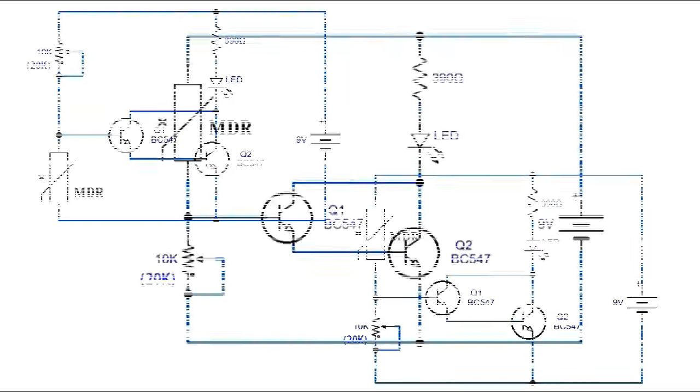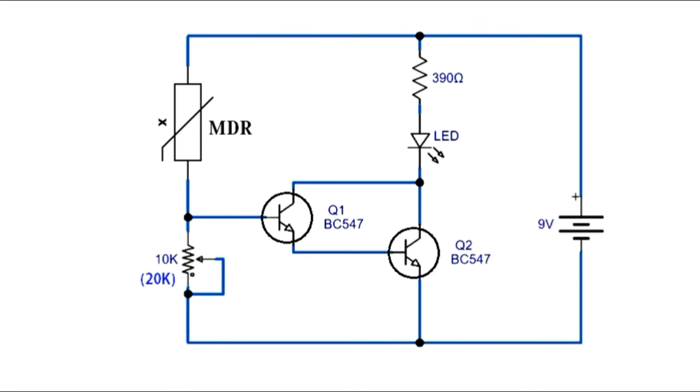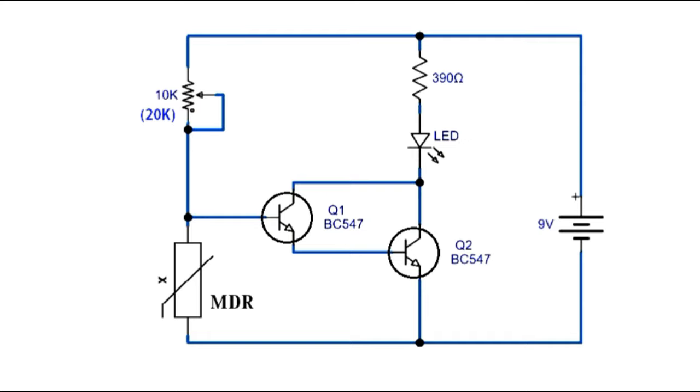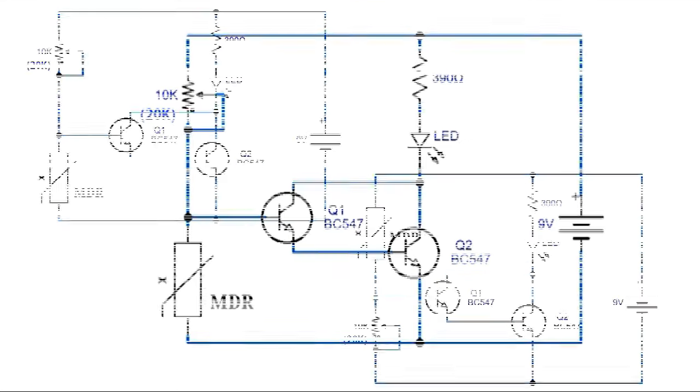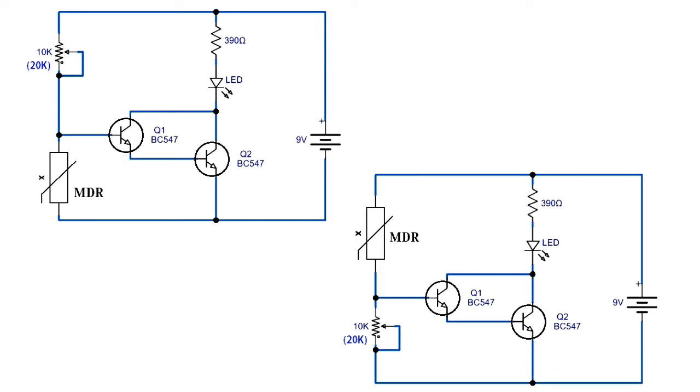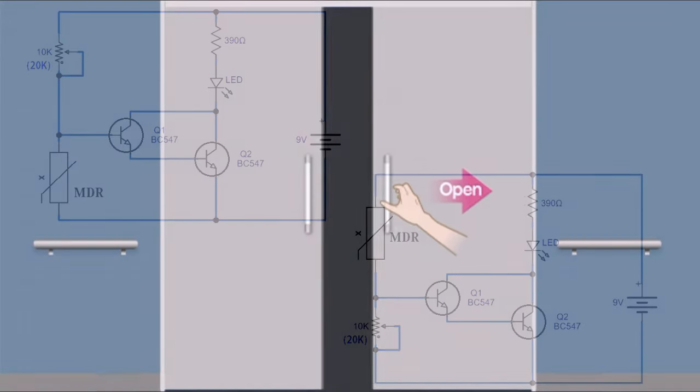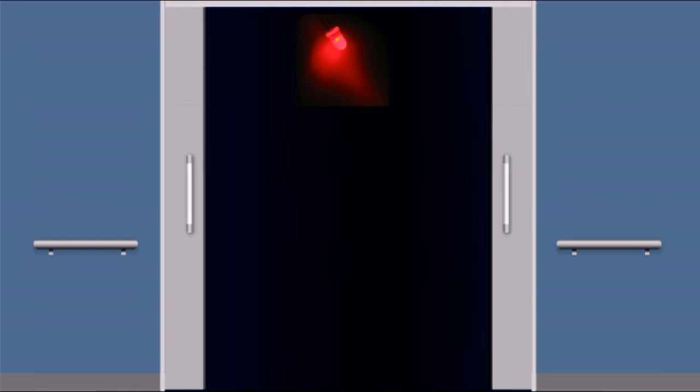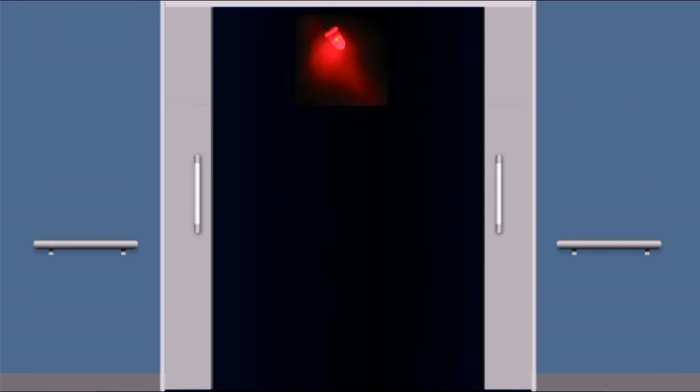The first circuit turns on the LED by approaching the magnetic field and vice versa. The second circuit turns off the LED when approaching the magnetic field and vice versa. Each of which will have its own users. For example, suppose you stick a magnet to the door. When the door is closed, the LED is off because the sensor is near the magnet, but when the door is opened, the LED is on, or vice versa. Instead of an LED, an audio warning alarm can be installed.